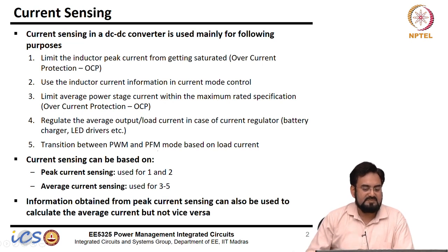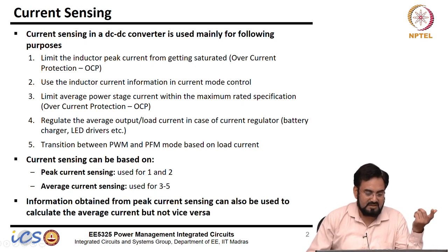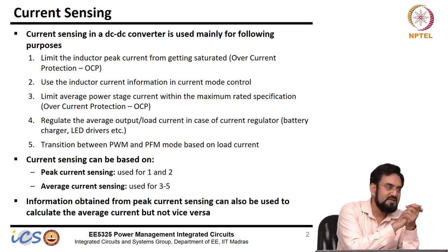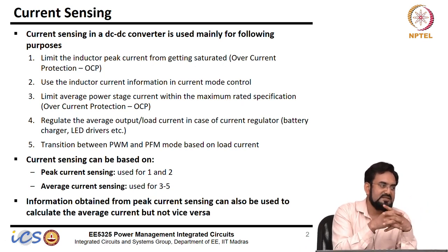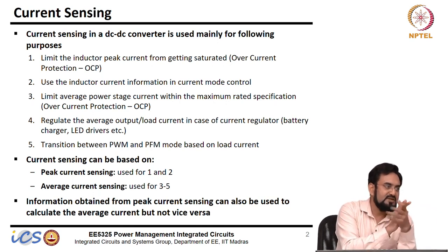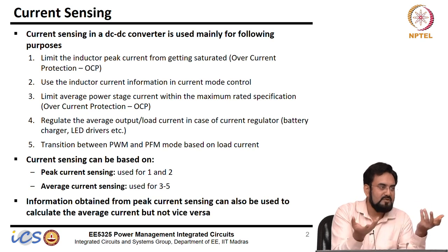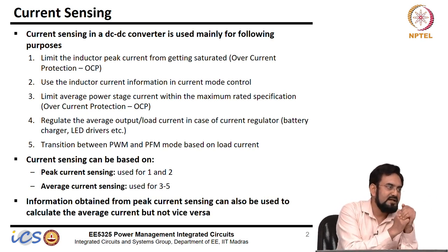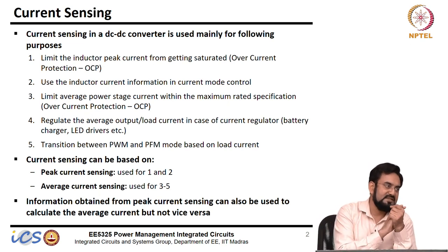Then another place which may or may not require it, depending on how you build your PFM mode. We talked about how you enter PFM mode. One is that you can detect a light load condition, or you can detect the DCM mode, and right away when you enter DCM mode you can enter PFM mode, or you can wait until your duty cycle is saturated. These two do not require current information. You know when the duty cycle is saturated, and you also know when it's entering DCM.